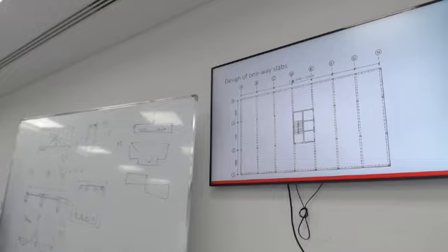And this is exactly how you reinforce the slab. You put steel on the tension side. If the tension side is in the bottom, you put the bar in the bottom. If the tension side is up, you put the bar up. How far do you extend the bar? Well, you need to go past the bending moment and then extend it a little bit because of shear. We talked about how the shear will add additional extension to the bar.